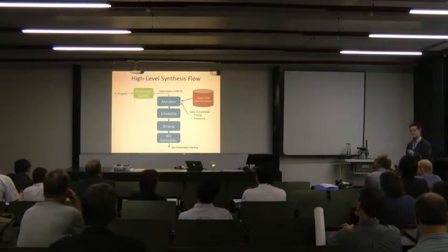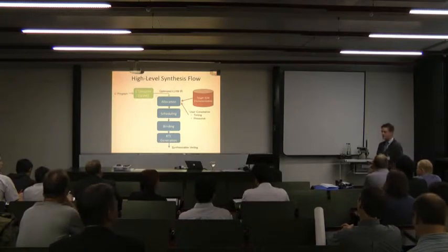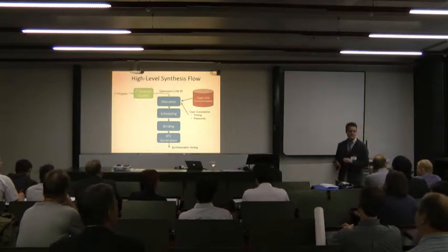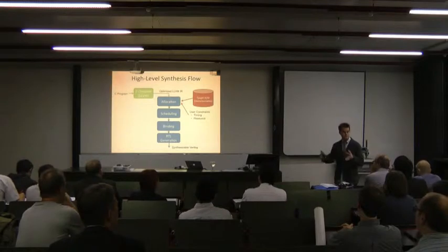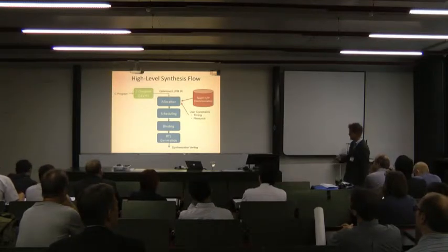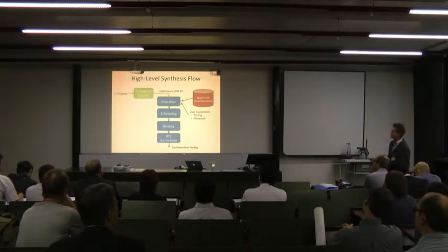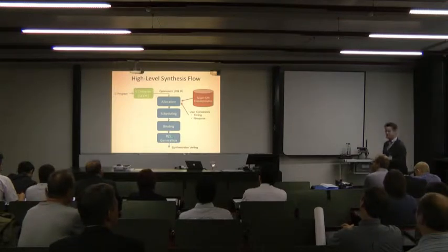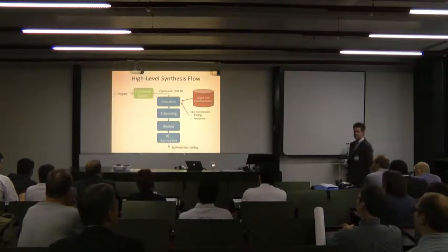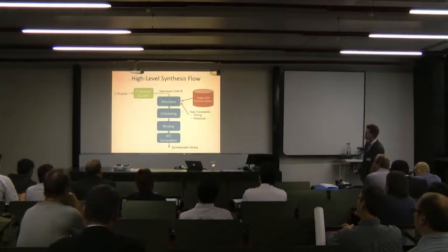Allocation relates to defining the structure of the hardware. How many floating point adders am I going to use? How many dividers? So it's really setting the constraints on the hardware. And of course that's based on user constraints and a characterization of the hardware. Then you have scheduling, binding, and finally generating the synthesizable Verilog. We'll just say a few words about each of these things.